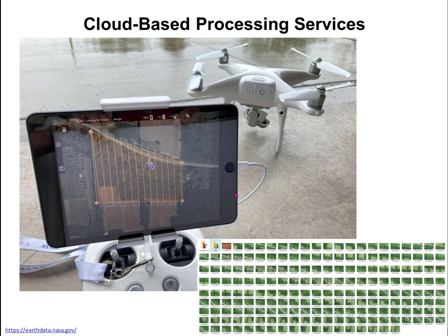I only show one example. I'm out here with my drone, and I had this flight program I designed for flying over a forest, and so I did it, and it's 165 images. It's got 2 centimeter spatial resolution. All of these are overlapping. The objective is to build a digital surface model of the top of the forest, top of the trees, top of the buildings, and an orthomosaic, a mosaic that's seamless across the whole area that is made up from these 165 images.